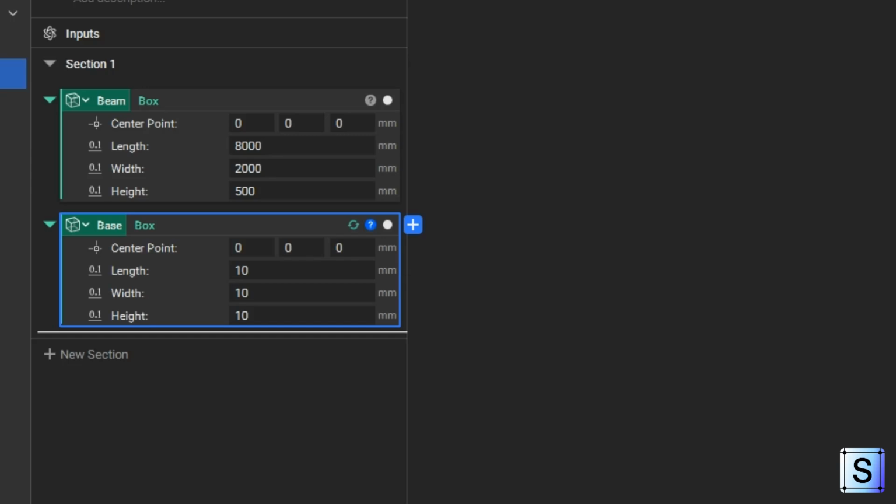And then we're going to have a small dimension in the length to minimize how much overhang we have. So we'll make the length something small, 200. The width, say 50. Height, say 50. And then we'll center this off in the end.